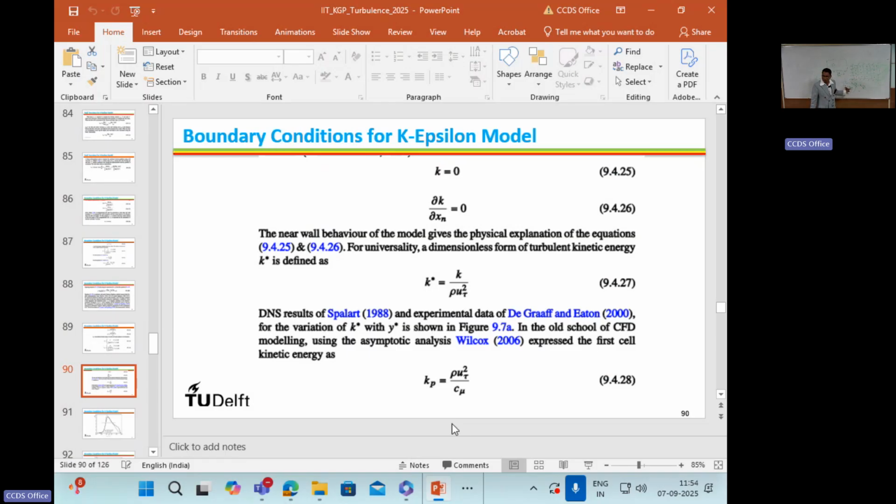This is the high Reynolds number approach. They don't solve the entire equation up to the wall. For the first adjacent layer up to the wall, the velocity is corrected from the wall shear, effectively by the eddy viscosity information at the wall, and the cell center velocity is updated.